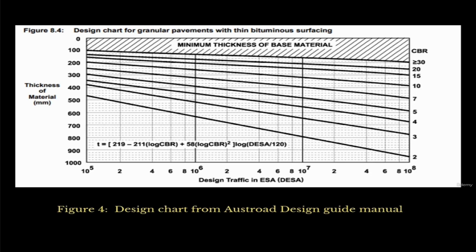That's your design traffic that you've calculated based on a traffic count. Or there's an app in New Zealand where it'll tell you the vehicles per day, so that's the daily traffic. Some councils have done traffic counts and they know the average vehicles per day for certain roads. So if you are lucky enough that you're designing for one of those roads, you can just use that app. You don't have to really have a traffic count, which saves you a lot of time and a lot of money.